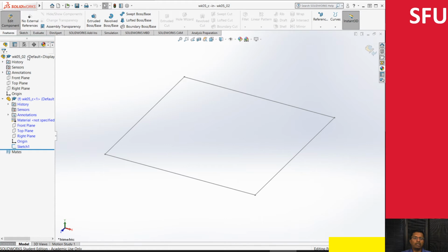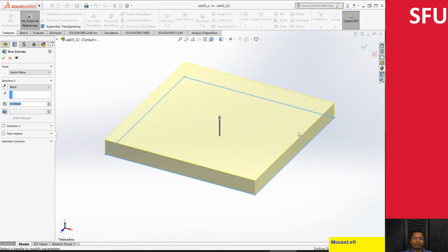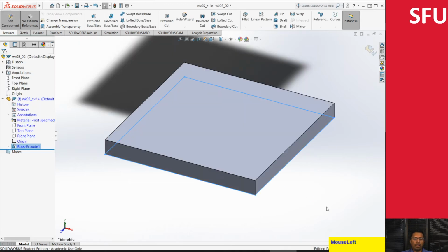Here, this might be useful, where it says whether or not you want to get external references. This might be useful when you want to use references from an assembly in constructing the sketch or the part itself. Right now I'm just going to click no external assembly, click on my sketch, and then click extrude. This extrudes it by 10 millimeters, and then I say OK.